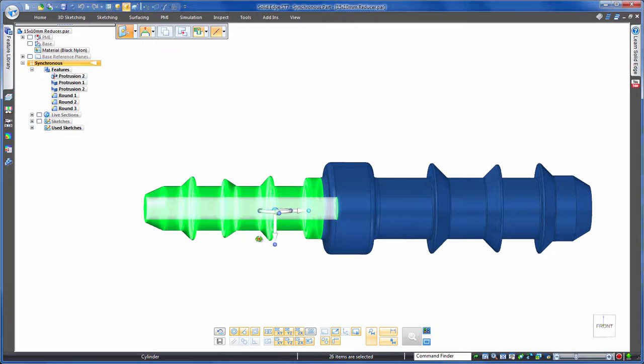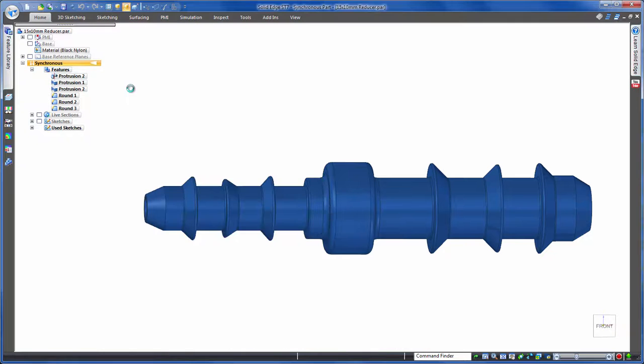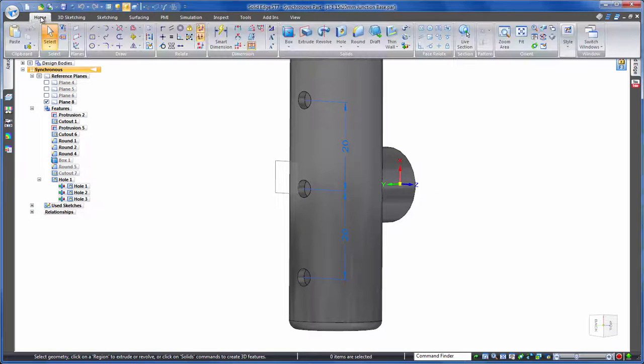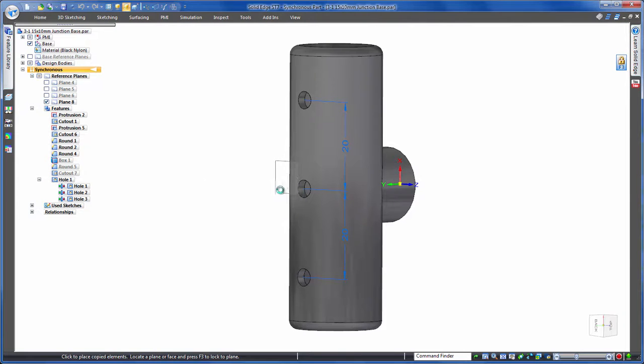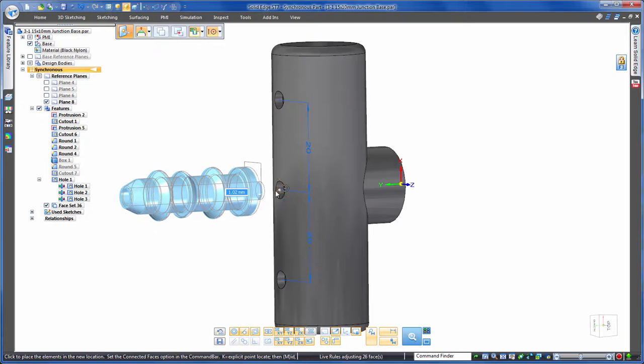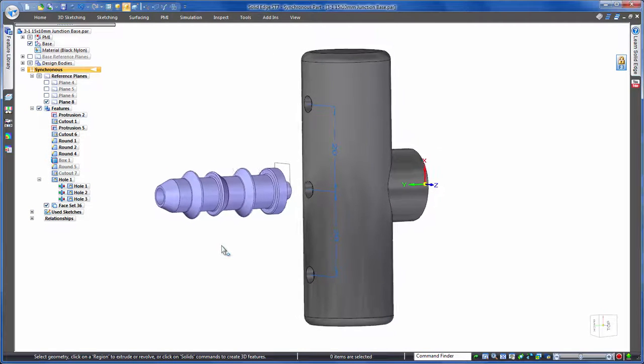Oh, and notice that we're moving what we call the steering wheel to a specific position. This is our main control for synchronous technology, and here it'll help us locate the detail in our new part. Then simply click copy, or use the Windows Control-C shortcut. Back in our custom fuel adapter, we just paste it in, again using the Windows shortcut Control-V if you like, and you can see our steering wheel is just where we left it,